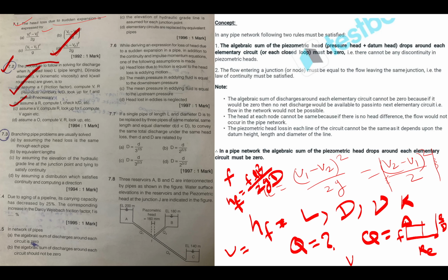This is the best procedure, because in this procedure there is no harm in considering the friction factor value, as per the material you can consider it, but you cannot consider your velocity or Reynolds number, because you cannot see by your eye whether the flow is laminar or turbulent. You can qualitatively find out, but quantitatively how will you find out how much is turbulent and how much is laminar.